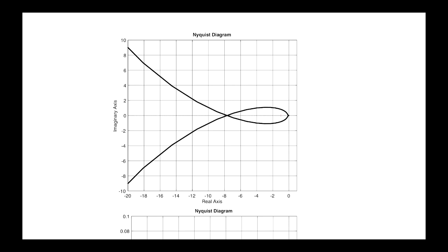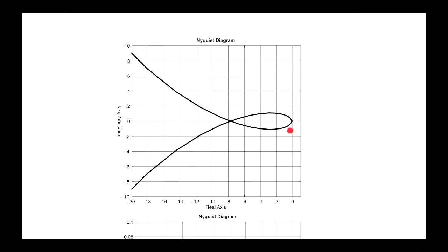In this particular example, it's hard to see all of the detail of the Nyquist plot in one shot, right? Because it's got this little bit in here that you can't quite see, and so in situations like that, I give you the zoomed in plot as well, right? So these are not two different Nyquist plots. This is just a zoomed in version of what's happening there, right? Because there's another loop that flips around in there, okay, and changing the gain could move the critical point from where it is to inside there, which will change the number of encirclements that you get, and that has an impact on stability, right? So this year there's a very similar question, right?